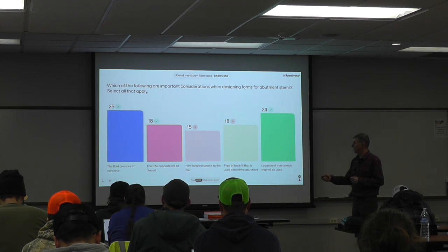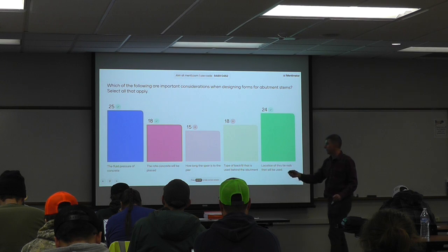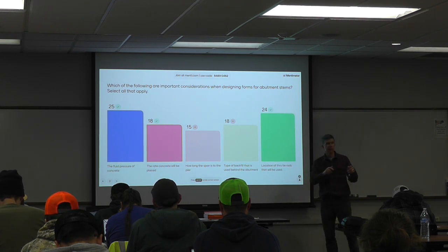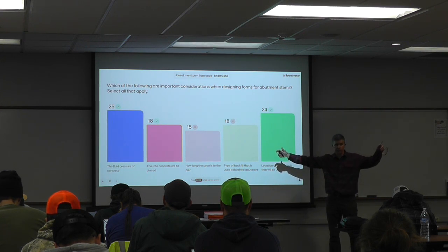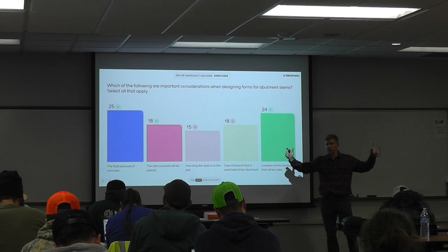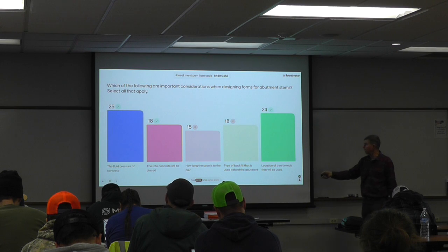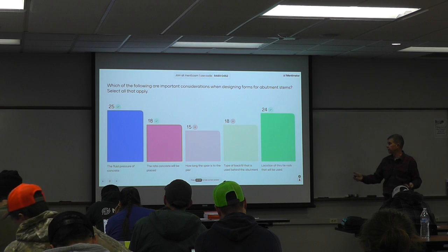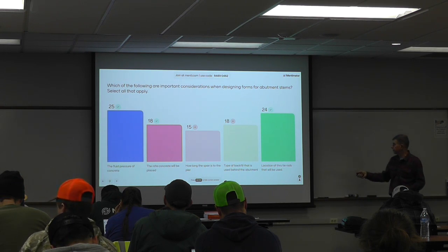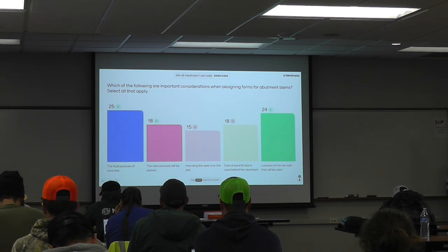How fast the concrete will be placed. The faster you go, the more pressure is going to be on those forms, so that has to be considered. And how long the span is to the pier, no, that really doesn't matter, because by the time we figure anything going to the pier, our abutment is cured out and it's strong, it's ready to go. Neither does it matter the type of backfill behind the abutment, because everything has been cured by that time. But the location of the through ties, tie rods do matter, and that's all part of what the forming engineer will come up with.